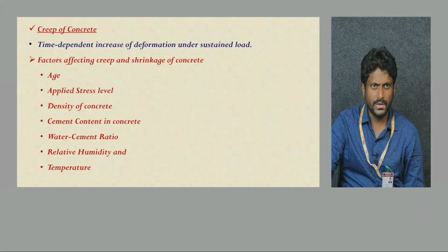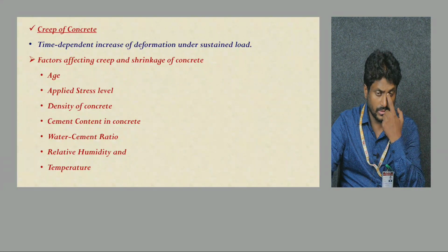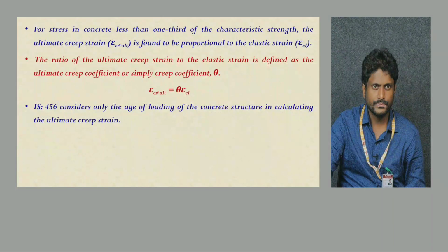What is meant by creep of concrete? Time dependent increase of deformation under sustained load. Factors affecting creep and shrinkage of concrete: age, applied stress level, density of concrete, cement content in concrete, water cement ratio, relative humidity and temperature.